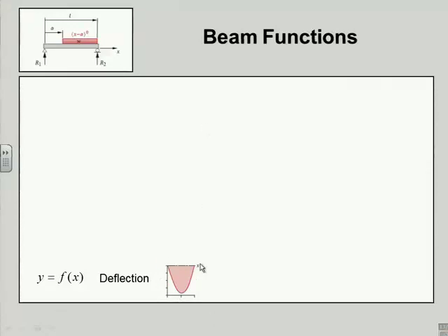And that is always a function of some sort, which we'll depict as y being the deflection as a function of x, where x is the distance along the beam, starting at one end as 0 and going to L. To get that equation, we have to work somewhat backwards. If we differentiate the deflection, we get the slope, usually called theta. So that's dy dx.